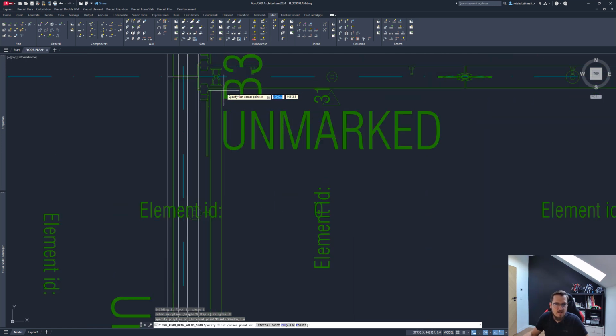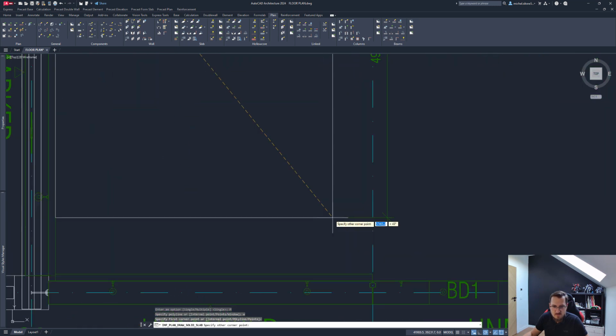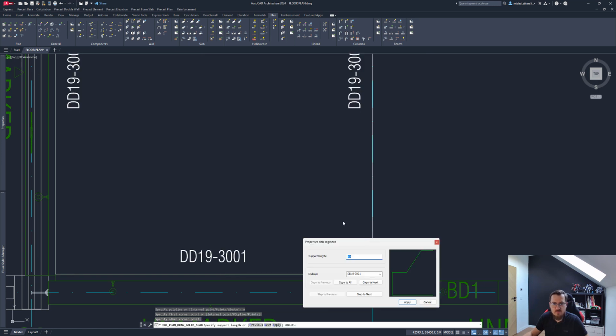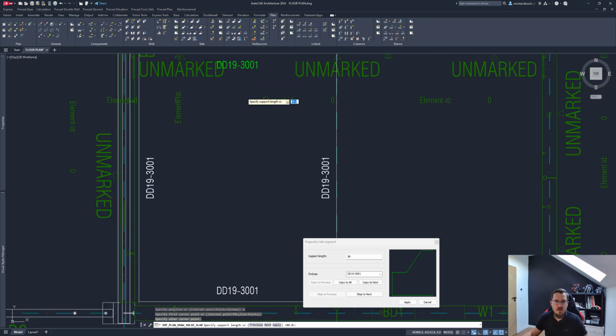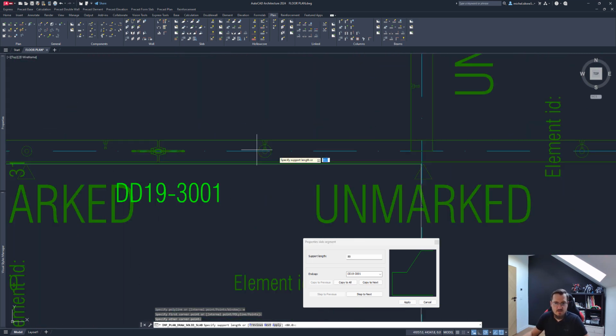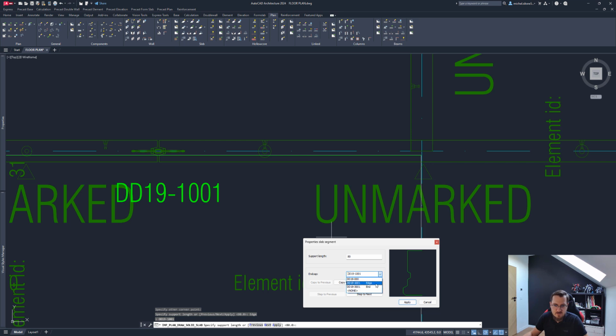So let's accept that. And let's place those multiple slabs, and let's place them by a window, right? So let me select that and I'm just going to grab that by this point and go to this point. It creates one big slab for me. No, it doesn't. What I'm now asked for, as was the case for hollow cores, is to add support and possibly change an end cap, right? So I can have different types of end caps specified here or just a plain straight end cap.